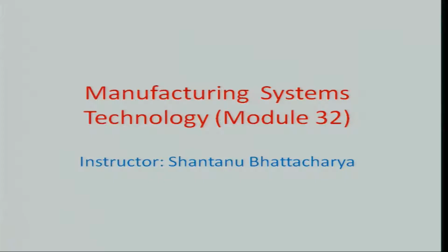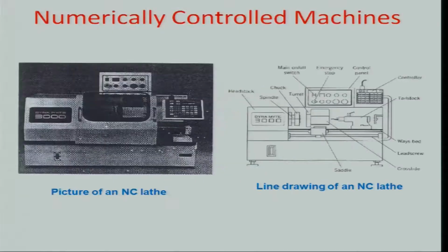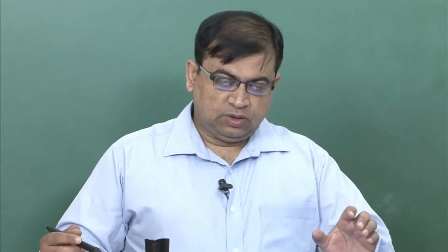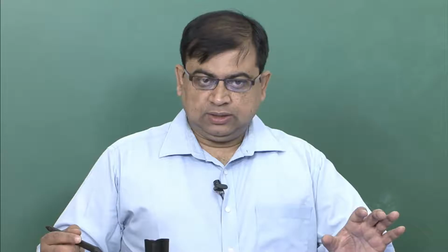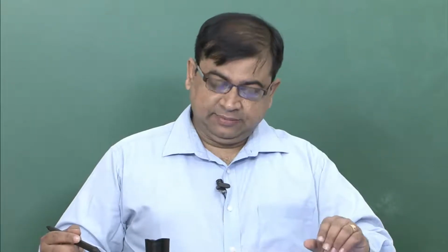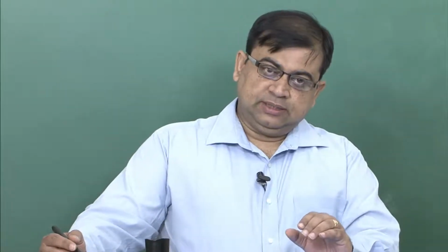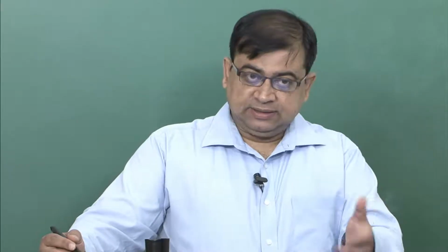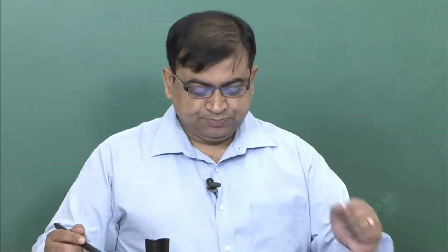We were talking about numerical control machines, and basically what we discussed in the last class was that they are no different than ordinary machines, except the fact that the relative tool to workpiece movement is now controlled through a controller process, and the human interface is avoided between the controller and the machine, although there is obviously a human interface between the controller and the external system which wants to develop a certain design in a machining center.